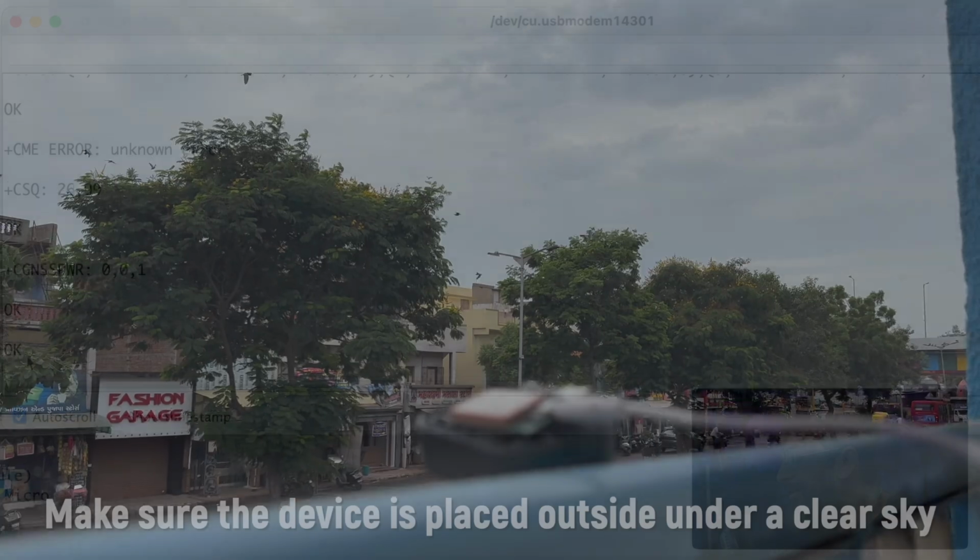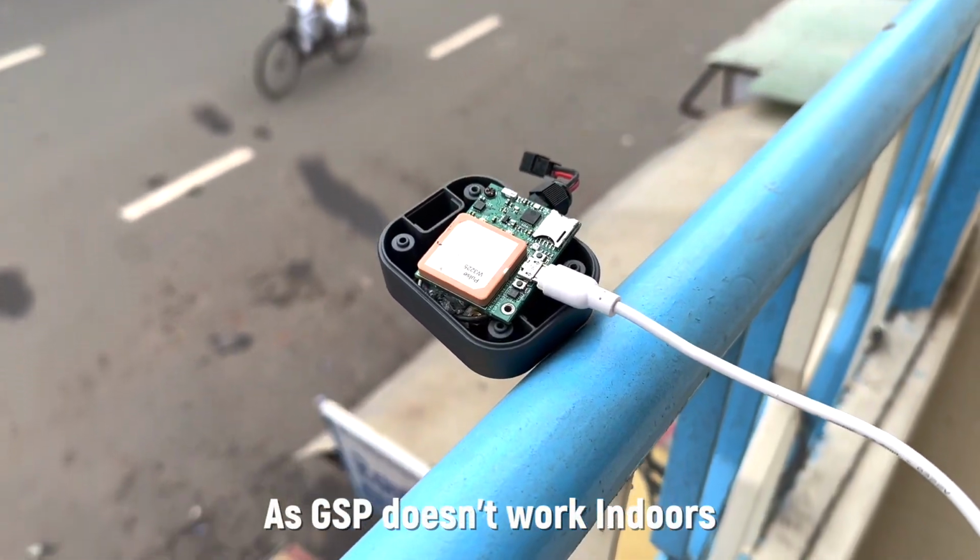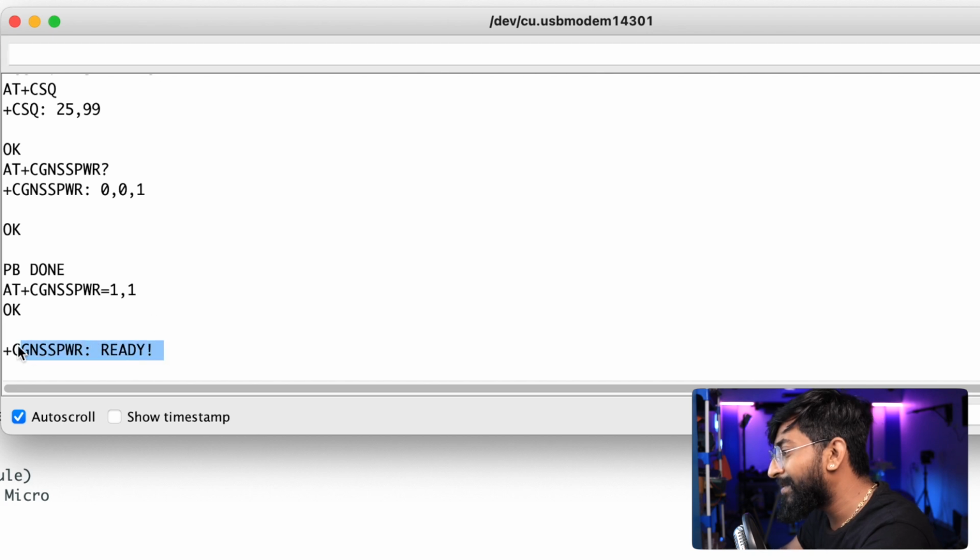Let's just wait for that command. Okay, so we got the CGNSS power ready. So initially I was not getting it, so I reset this using the command AT+CRESET. Then again I provided this command, and now I got CGNSS power ready. Now this is a very important step. Until you get the CGNSS power ready, you won't be able to do all the GPS related tasks.